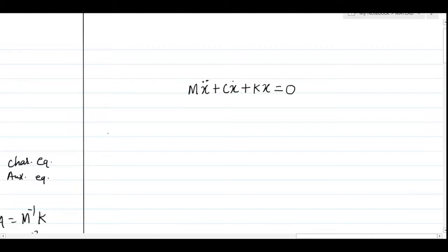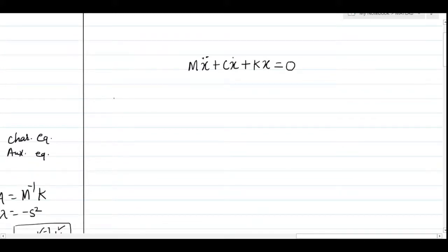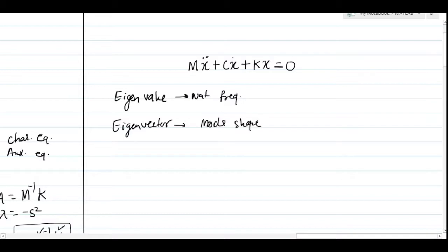So when you solve the eigenvalue problem for a damped system, particularly I am talking about eigenvalue, because the eigenvalue problem will give two things. One is eigenvalue, another thing is what we call eigenvector. Eigenvalue gives the natural frequency and eigenvector gives the mode shape. But both are complex. In case of eigenvalue, you get a value alpha plus i beta. In this statement, alpha indicates the decay, and for a normal system, alpha is normally a negative value.